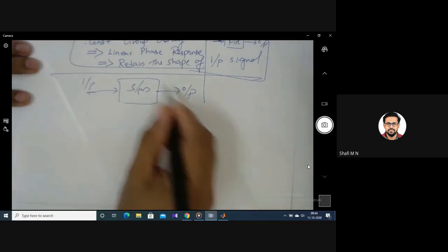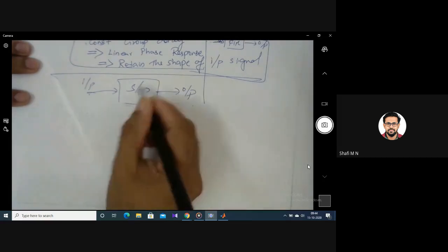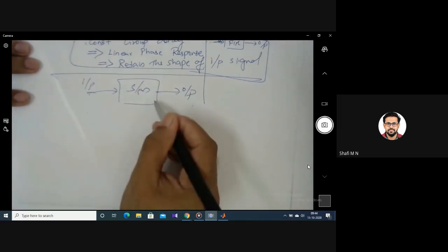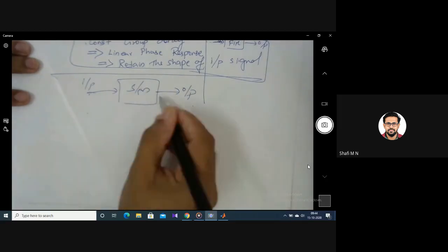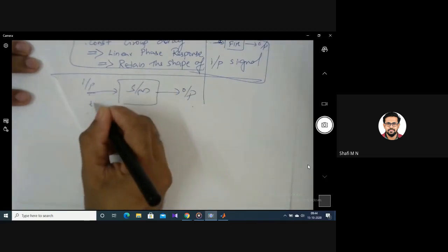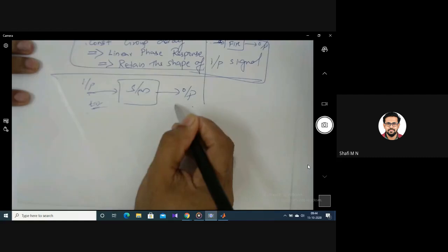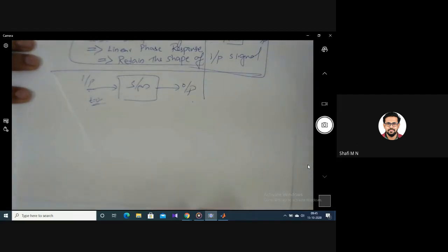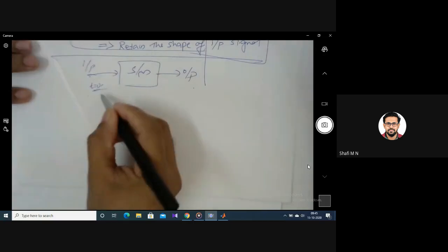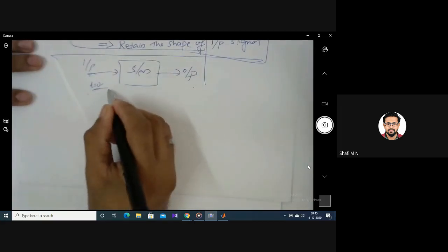In between you have some circuitry to do the required processing, say required filtering. When you give t=0 to this filtering, at that very instant you do not get the output at t=0. There will be a delay. You are going to inspect that. So when a signal reaches there, phase delay is usually applicable to a single frequency.